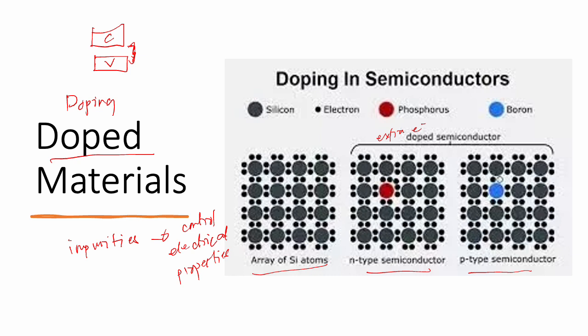While for the p-type, the idea is that it has electron vacancies, or holes, extra holes, which can enhance conductivity but in a different way. Holes can accept electrons, making it easier for them to move to the conduction band, reducing the effective band gap.